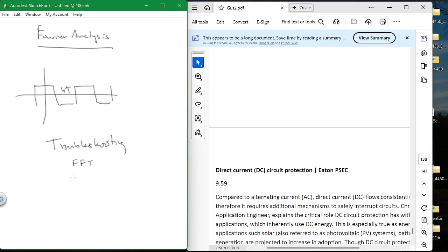As these harmonics start to grow, they tip you off that something is going to happen. There's a bearing that's going to go bad, probably mostly mechanical, and things start deteriorating very quickly after you see these FFTs starting to go.